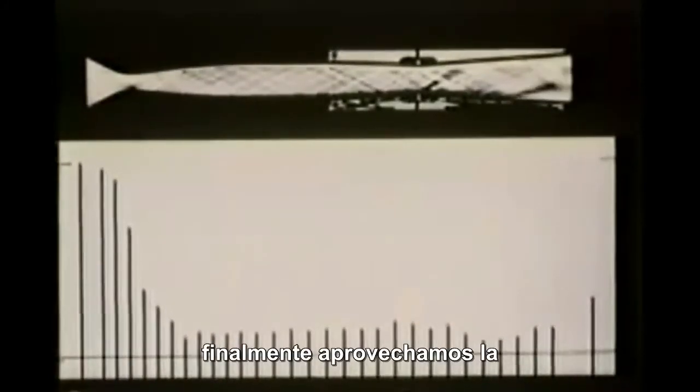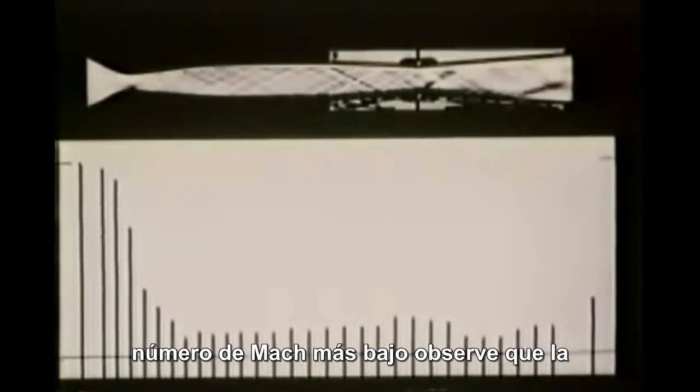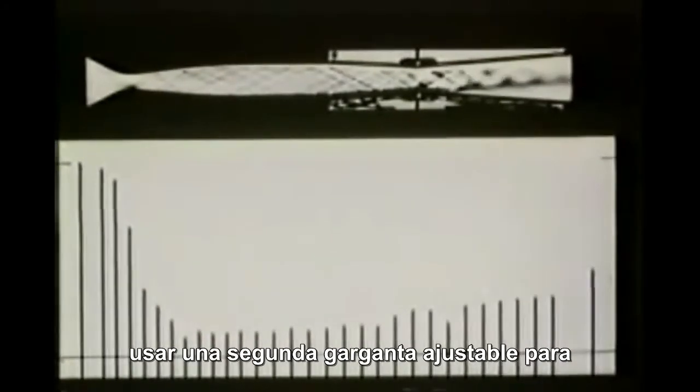Finally, we take advantage of the supersonic compression by closing the control valve a little to move the terminal shock pattern upstream to a lower Mach number. Notice the downstream stagnation pressure increasing. Now we have reached an optimum running condition with a relatively low dissipation of energy. The advantage of using an adjustable second throat to control the airflow is that the stagnation pressure losses and hence the power required to run the channel can be reduced below the requirement for starting.